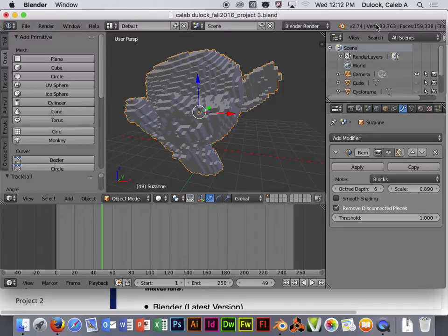That tells you how many faces or vertices or triangles the particular object you have selected on screen is made of. Again, my screen is truncated because of the projection conversion, but yours you can probably see all of those numbers listed across the top. And you want to be very careful with how many of those you have, because the more you add in, the slower Blender or your computer will run, or the faster it will crash. So just be aware of that stuff.